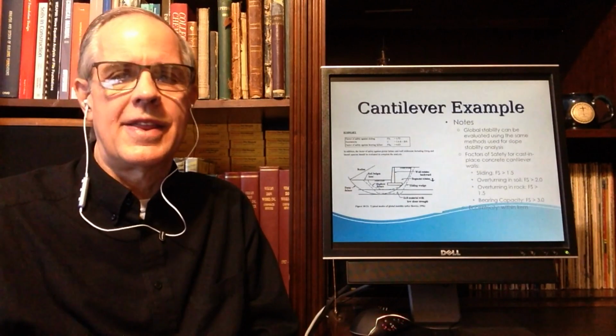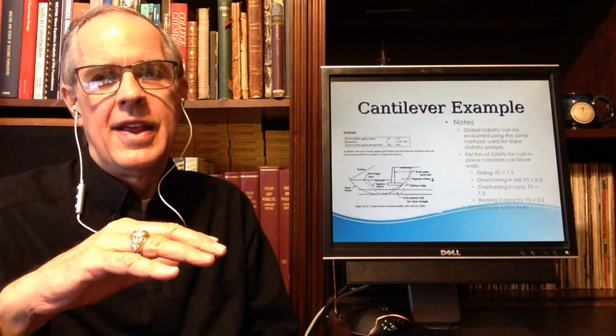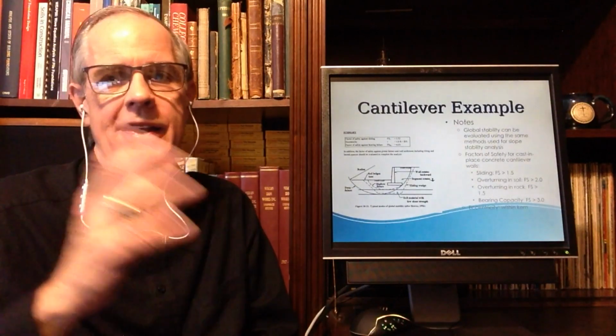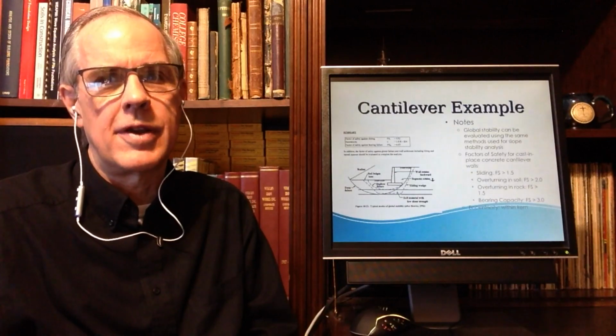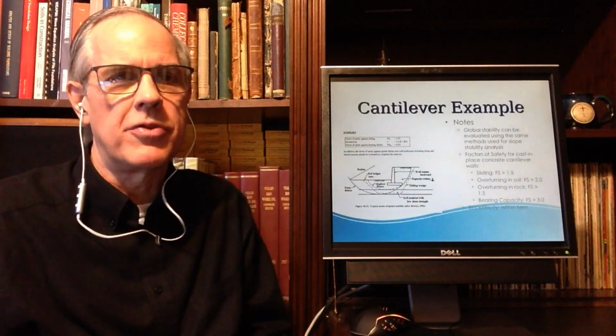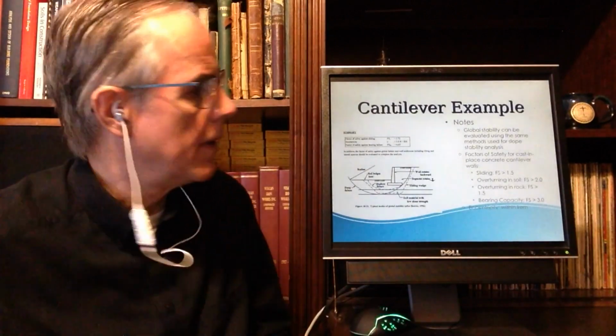Many retaining walls like this are founded on good soils. If they're not, they very frequently will put piling or some other type of deep foundation under it. But if they don't need deep foundation, they need to be checked for settlement. Or if they're kind of in a middle sort of thing, they need to be checked for settlement. Settlement's important.